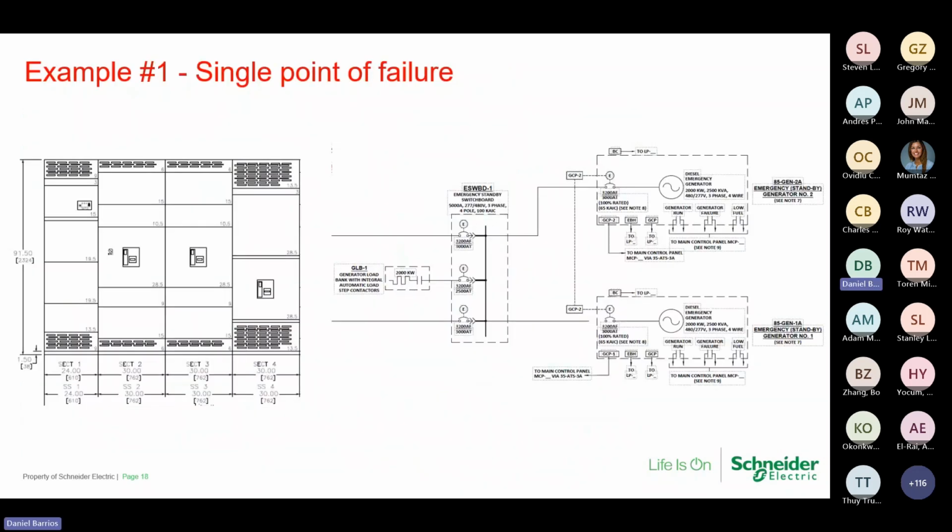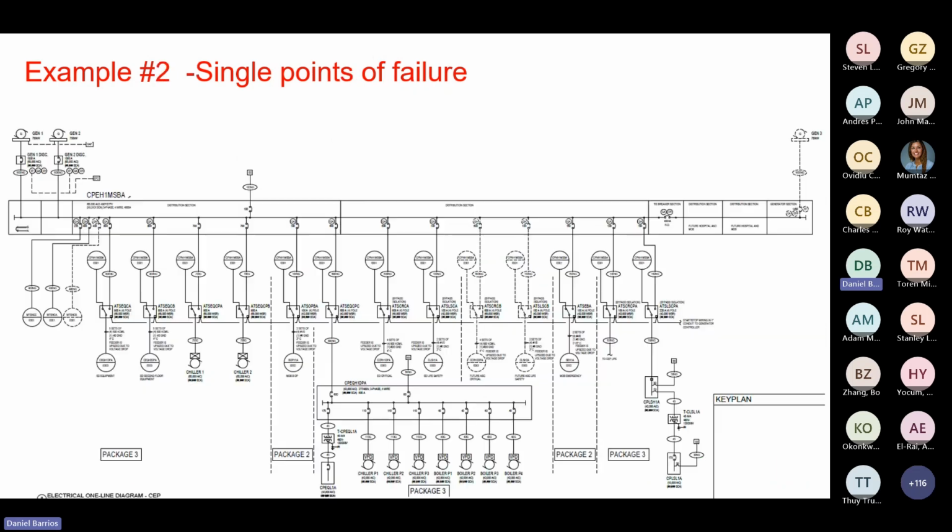Well, why are we concerned with this, folks? It's simply to point out to you, if you have these two generators and you're connecting them to a main lug only panel, you may have a point there that you're concerned with. Should you have a fault, you've taken out your whole system by not being able to clear a main breaker or by having it just connected in this capacity or such.